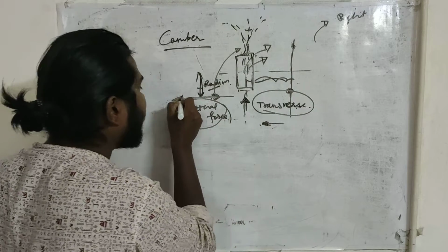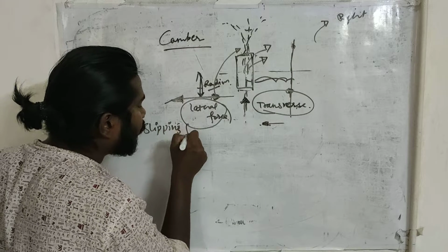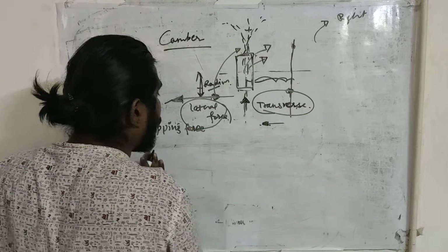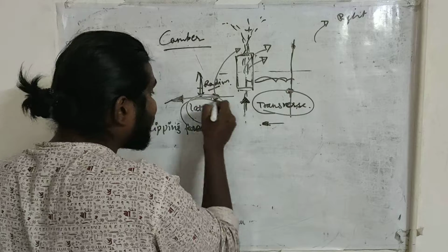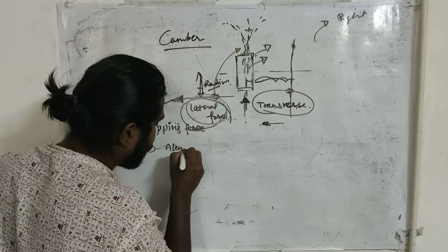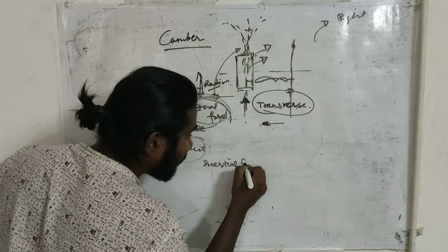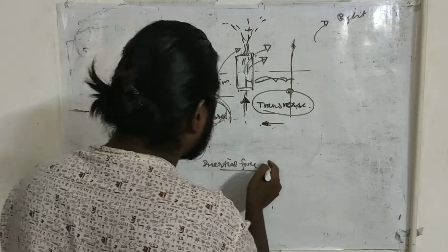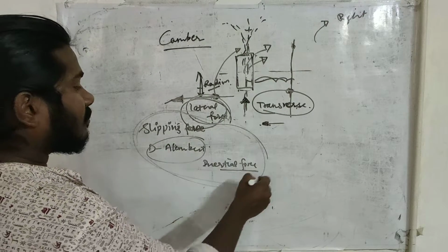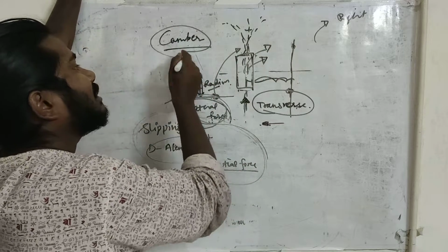The lateral forces that are acting here, the first force that will act here is the slipping force produced by the tire. That is an inherent property of the vehicle. The second force, the lateral force that I am talking about, is the D'Alembert force, the inertial force. The change in load that is occurring in the vehicle. Now these are the transverse forces, these are the lateral forces that are acting on your tire to cause the camber change.